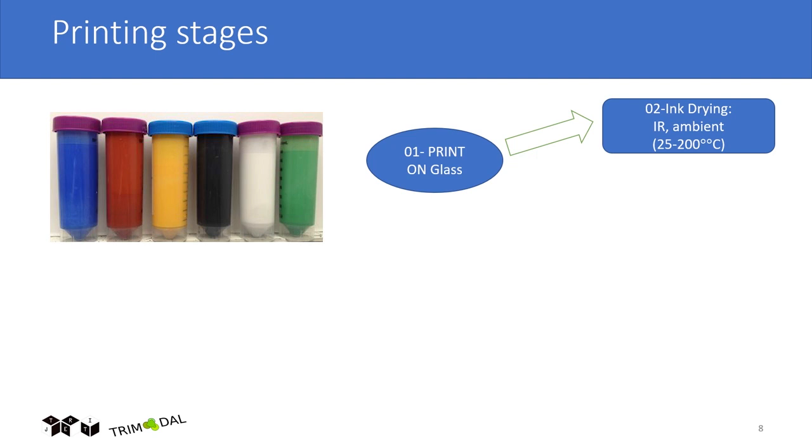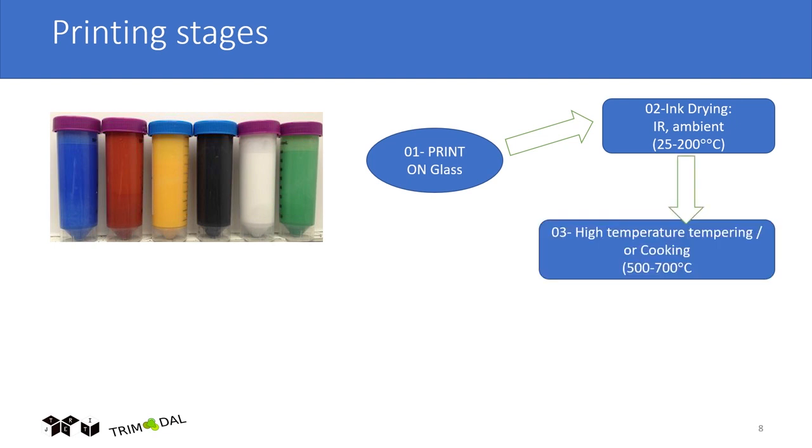But remember that resin, now, when I go into the tempering stage, I need to burn that, right? And that's at 500 to 700 degrees Celsius. I will cook it. The glass fuses it. It forms a part of your glass, yeah? And that's why, even the Coca-Cola bottle, you see the Coca-Cola white is a thermoplastic ink, but it's a frit and a pigment, right? So you get scratch resistance and all that. That's what you get.